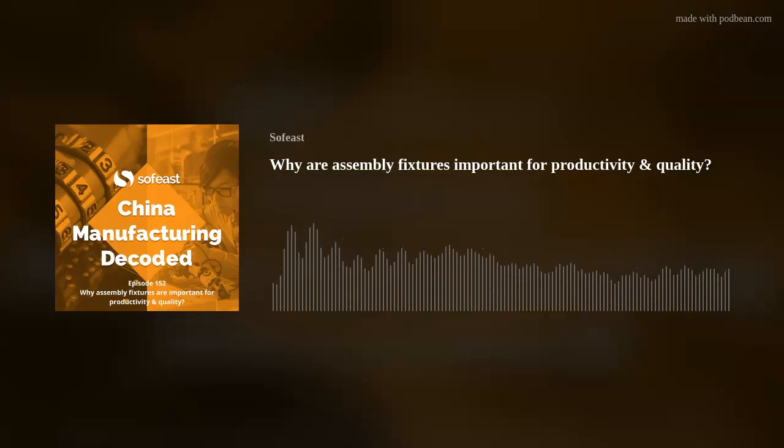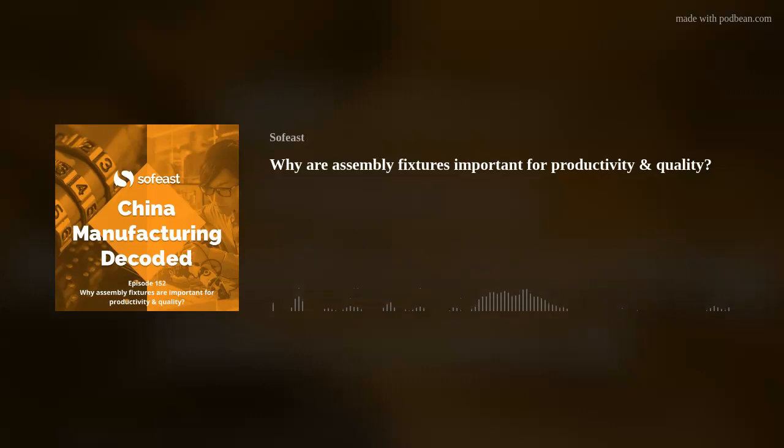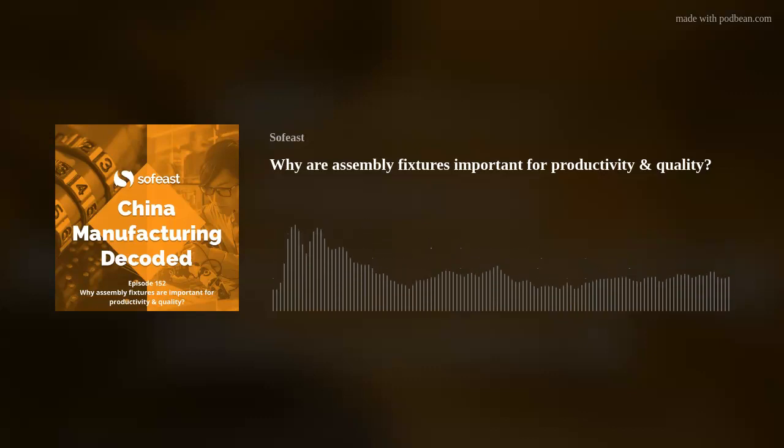It's a fault finding nightmare. But one of the simplest things to do is you've got a fixture that lays out the loom. We call these the wiring harnesses or loom. And you basically plug in each of the plugs, right? And that will give you a continuity. Make sure you got A connects to A, B connects to B, and you'll get the signal. That can be a sounding signal, a light signal, or whatever signal it is to say, yes, everything's working. Or more importantly, that this checking fixture allows you to identify the fault before you assemble a very complex wiring harness into a vehicle.